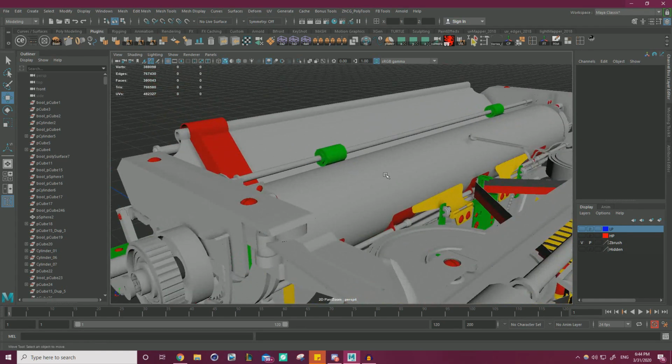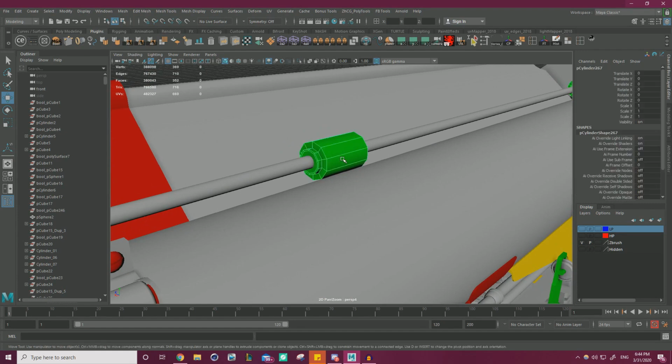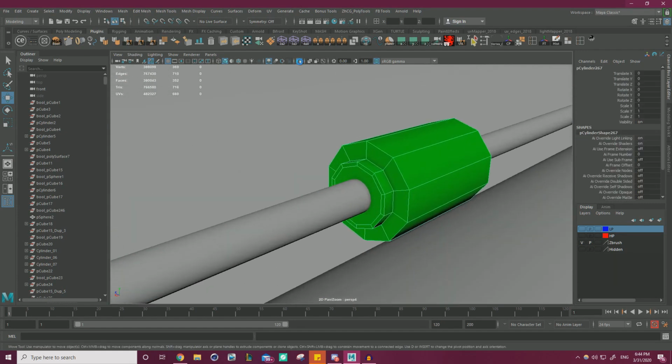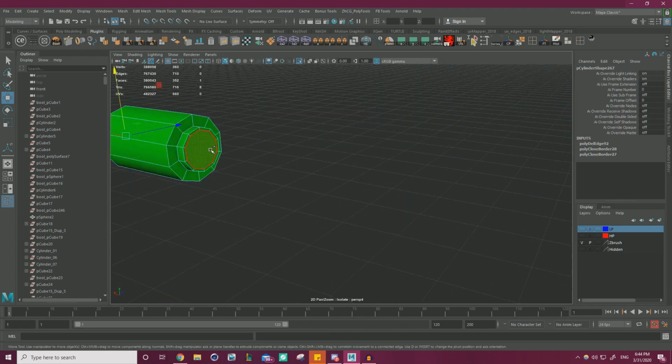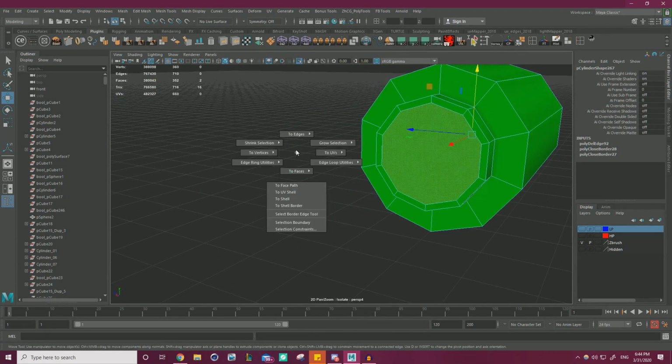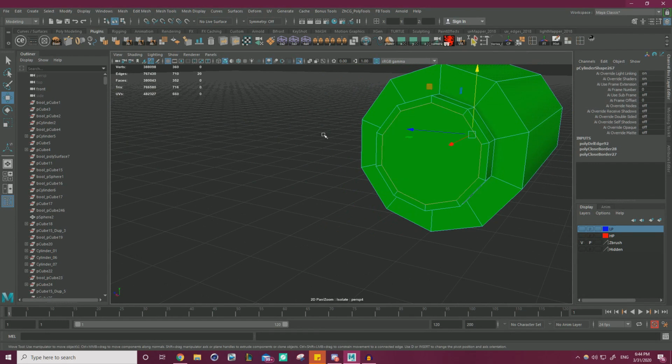So let's move forward with that. Let's delete these edges that we really don't need. So I'm just going to grab those and hit Control Backspace, and then we can just cap this off like we would everything else.